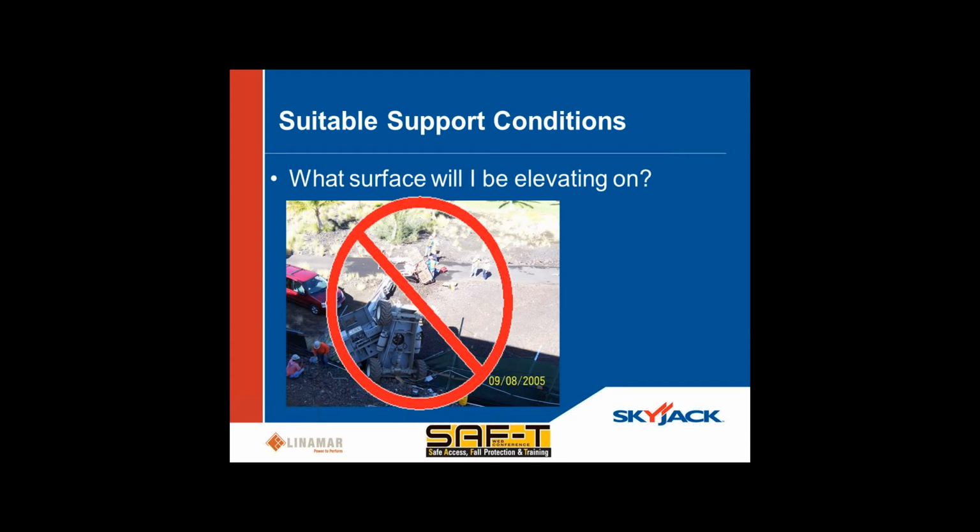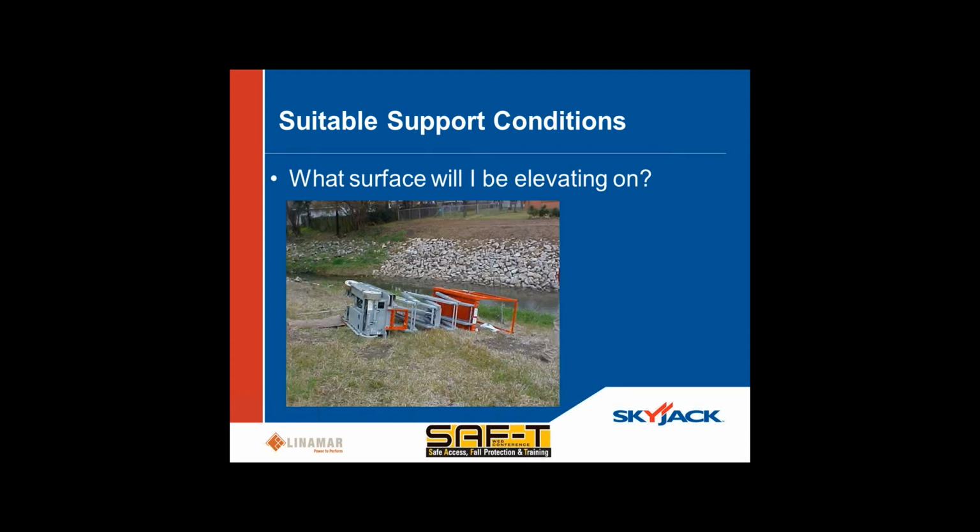And that may be true as well, that in a construction site type example you may actually have to do ground condition improvements or leveling or compacting of ground to ensure that on your construction site, if you're planning on using an aerial lift in that particular application, you have suitable ground conditions. And so you may have to choose a particular lift that is suitable for that, or you may have to alter the ground conditions so that they're suitable for the lift, either or. But you do have to think about those type of things when you're choosing the lift.